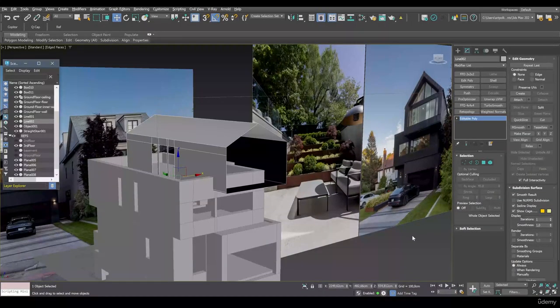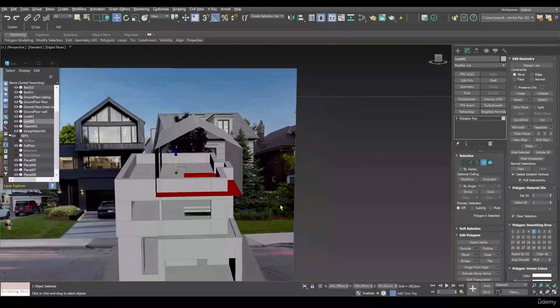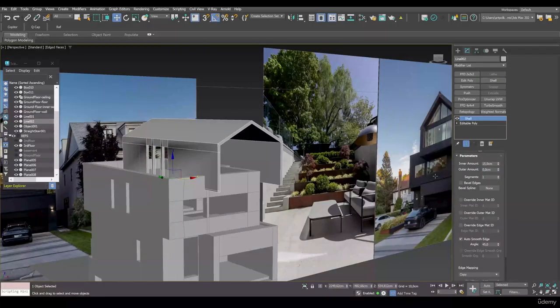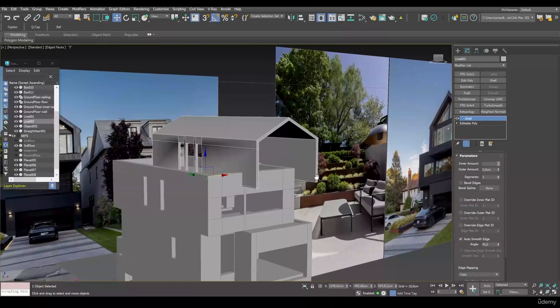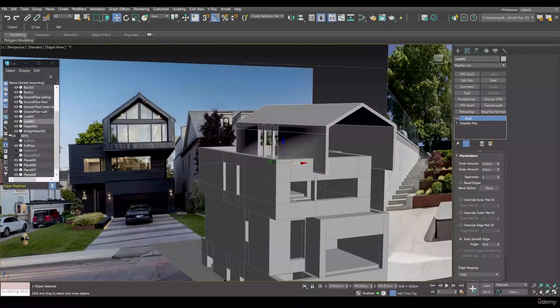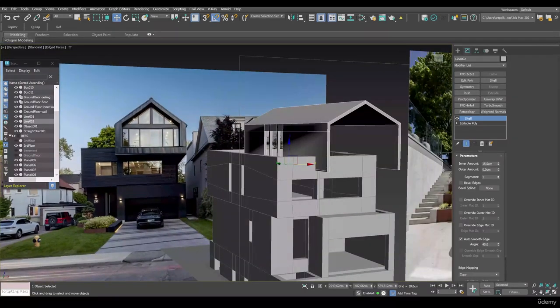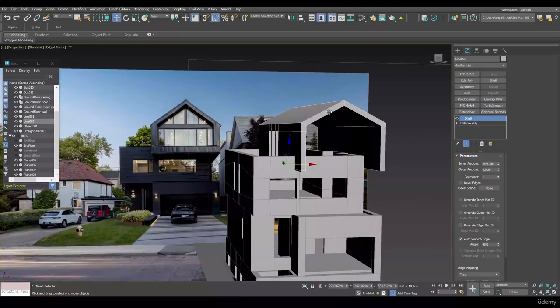And so before we set thickness to these walls, I'm gonna go ahead and delete the bottom polygon and assign the shell modifier. And we don't forget to look at the photo, at the thinnest part, and we can set about 30, maybe even 25 centimeters, 25 to 30.